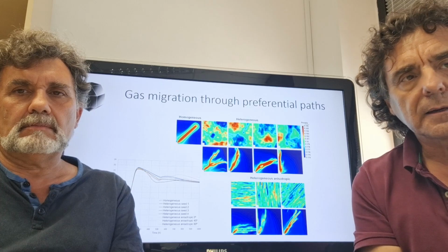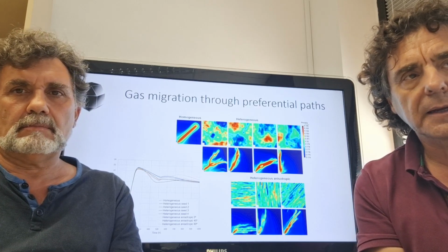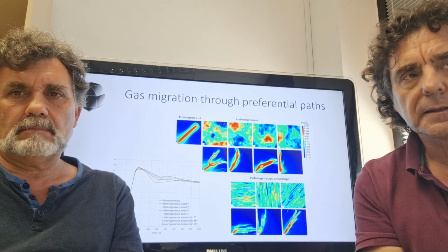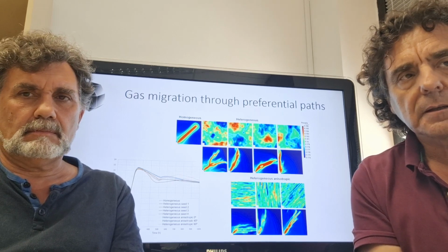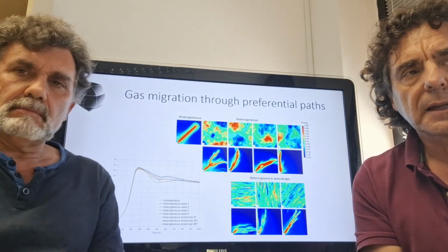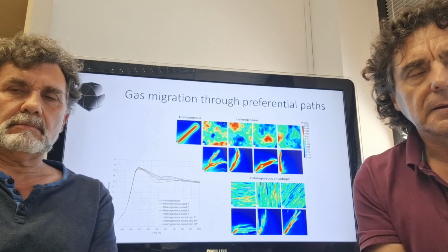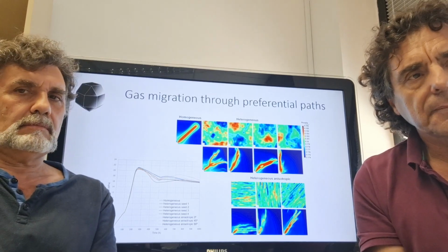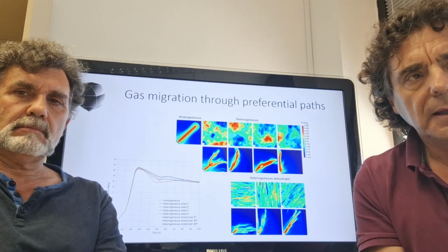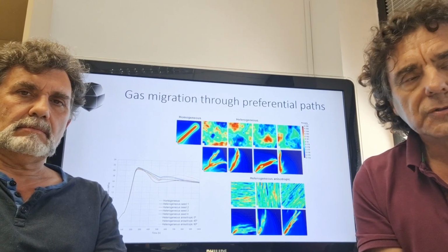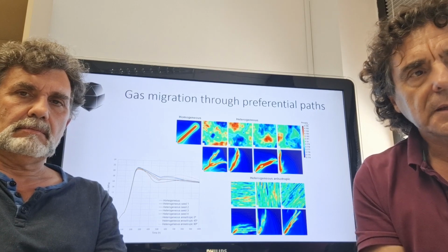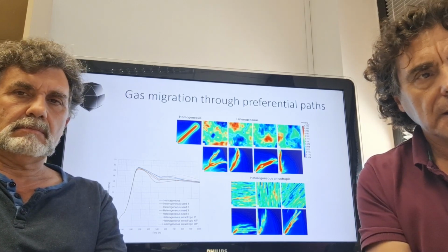Thanks to this, we can solve these gas migration problems, which are related with the gas generation induced by several chemical processes like corrosion or organic matter degradation, and then this gas migrates in isolation barriers, which are very low permeability geological materials like clays, and then it's very important to have this capability to incorporate heterogeneity.